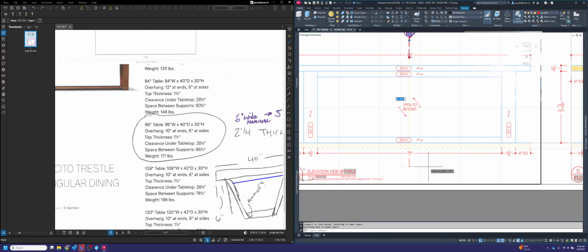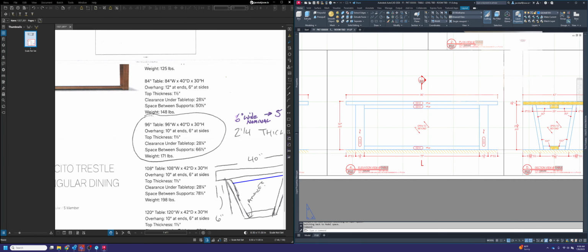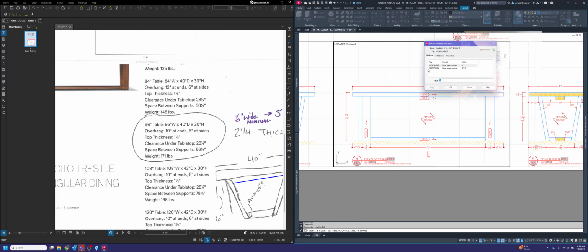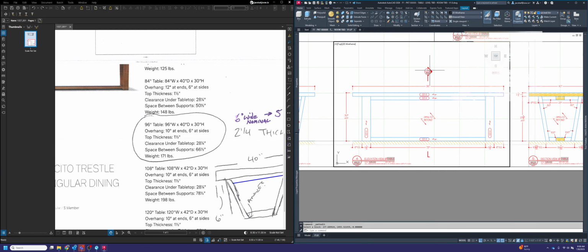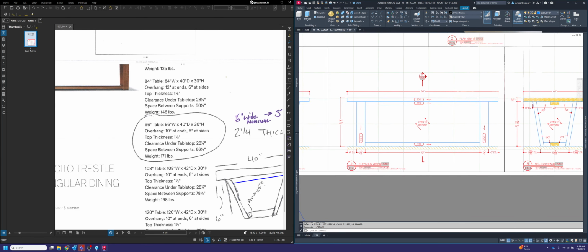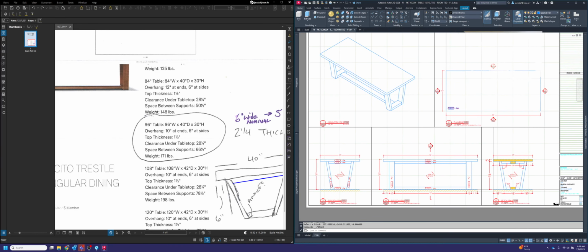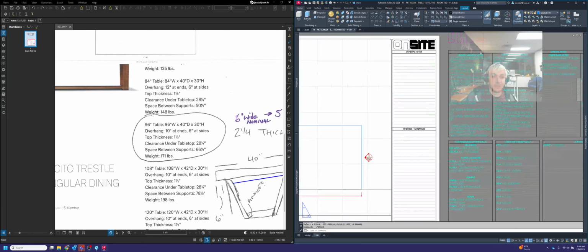And we're going to make sure that the tail and the head of that section call do not intersect the drawing at all. So make sure that they're hovering off the side of the dimensions and the view. And then also be sure you have the correct view number and the correct page number for that. Lucky for us, everything's on one page, so it does make things easier in that sense. So then I think we should be all set there. And then what we want to do is move on to page notes.